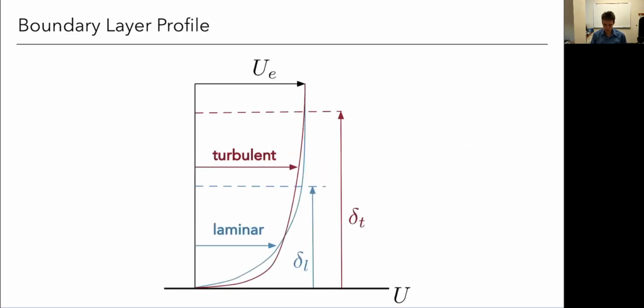So again, hopefully by way of review, this is just a picture of the laminar and the turbulent region. An important distinction here is that a turbulent boundary layer has a higher velocity near the wall. So let's think about some of the reasons why this occurs, and also some of the engineering implications. The laminar boundary layer refers to layers, so we could think of it conceptually as separate layers of fluid, each passing somewhat independently, right? Slower and then faster and faster as we get further away. That, of course, isn't a perfect image. There is some mixing, but it's a relatively small amount of mixing, and so most of the mixing that occurs is at the molecular level, as we've discussed previously. So really small scale mixing.